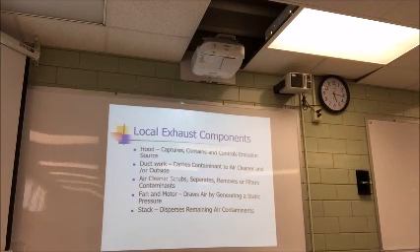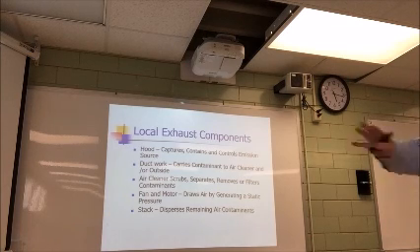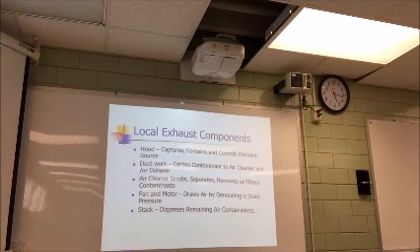So what were we doing on dilution ventilation? How were we protecting people? What was happening to the contaminant? It spreads out, so it's not as dense, doesn't have as much mass. What are we trying to do with local exhaust ventilation? Remove it. That's the difference. One spreads it, one removes it, okay?